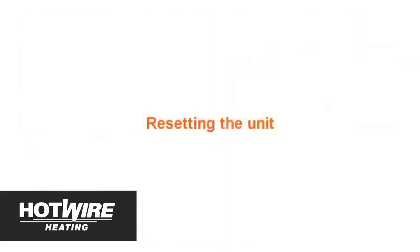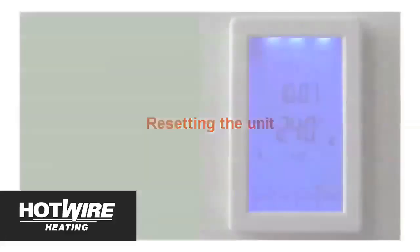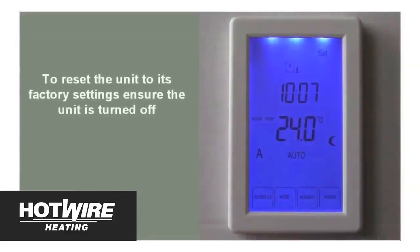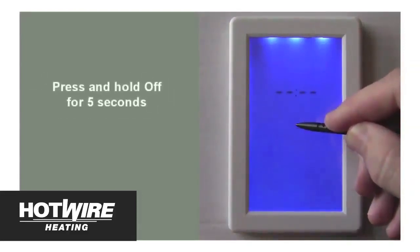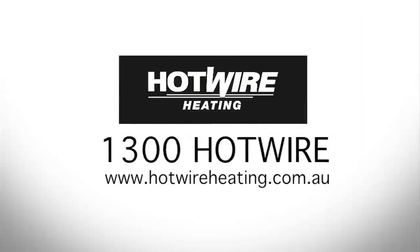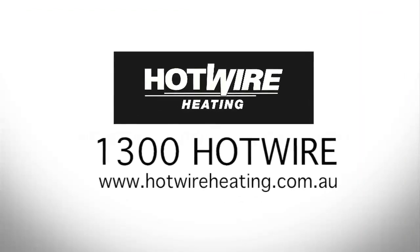Resetting the unit to its factory settings. To reset the unit to its factory settings, turn off the thermostat by pressing the power button. Then press and hold off in the center of the display for 5 seconds. The unit has now been completely reset.